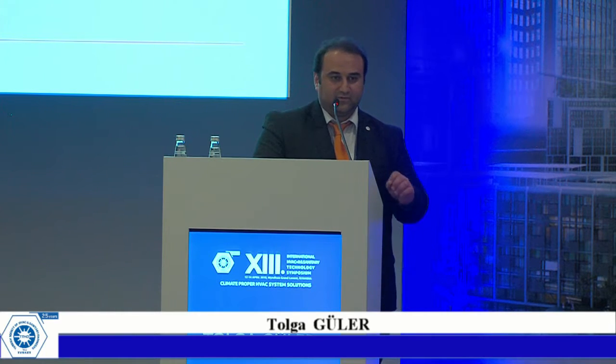Our modeling approaches: the first is grid modeling. In grid modeling, either a full CAD model or a reverse engineered CAD model can be used in the analysis, and we have 5 cells between the neighboring fins in the grid model approach.